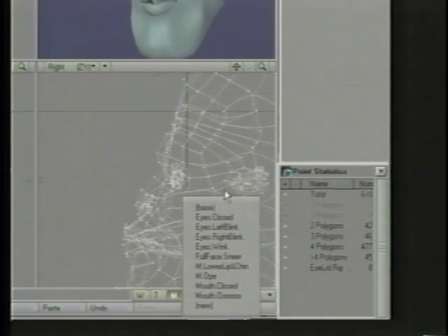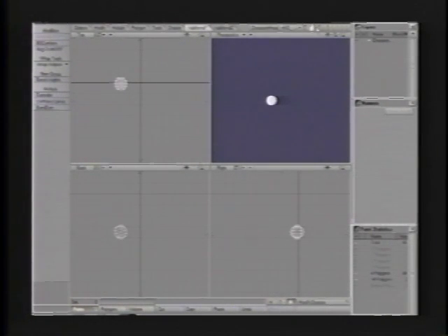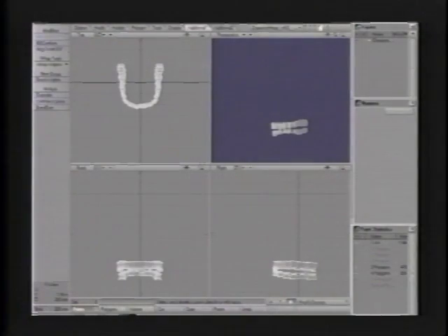Now, something that's important to keep in mind, when you're working with layered objects, these background layers here, the eyes probably aren't going to be affected, but the mouth layer was kept separate. And this has the same exact targets as the other one. So you want to make sure that when you're adjusting those morph targets or those endomorph values, that you have all your layers that are pertinent selected, because as you're changing one, you're changing the others as well. Okay, once we have these things all renamed, we can take this then into layout for animation.